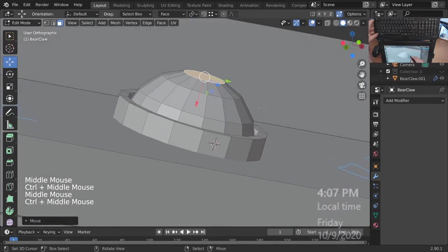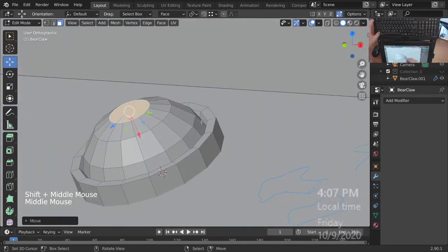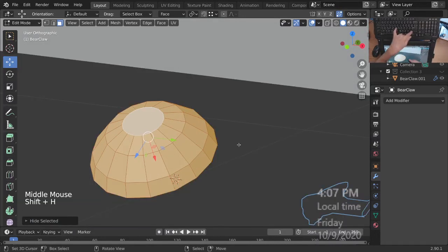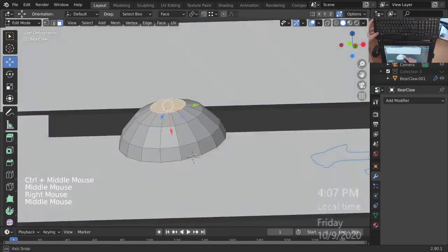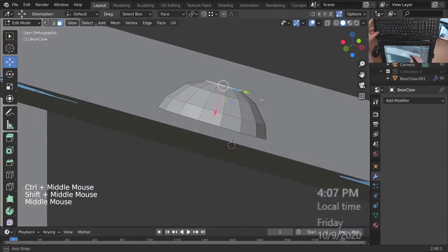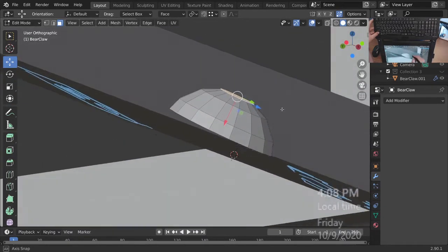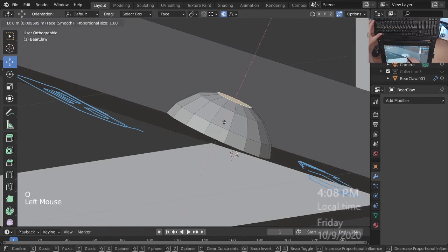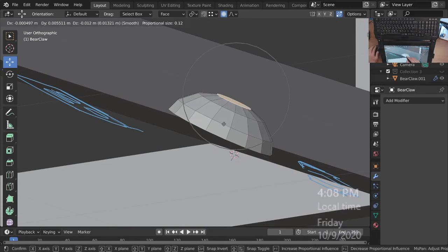It looks like a button that you push. It's a little bit big. So let me go Control plus, Shift H, and let me take that one and then just with the proportional editing on, grab it and push it down, and then just there it is.